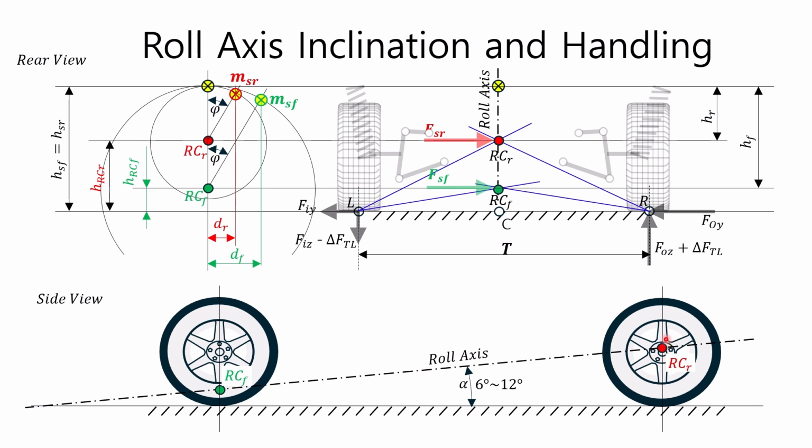It is true that most vehicles have a lower front roll center than the rear, leading to an understeer tendency. However, a forward tilt of the roll axis does not necessarily lead to understeer. In fact, rather, contrary to this belief, a high rear roll center can lead to a tendency toward oversteer.